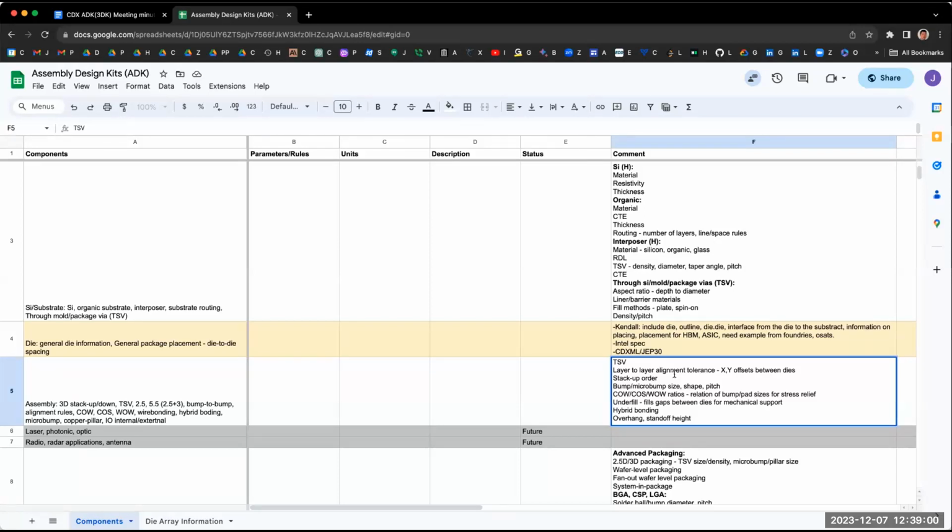So they're going to use these assembly design rules to make sure their chiplets are meeting those rules. And if they don't meet those rules, then they're not going to be able to integrate it on that interposer. Now, it's easy if you're a single vendor like TSMC and all the chips are coming from TSMC, and they're building the interposer, so they're mandating what that is if you want to integrate it with TSMC. And everyone supports HBM, so that's a given. But there's other rules that need to be dealt with, so they're manufacturable.